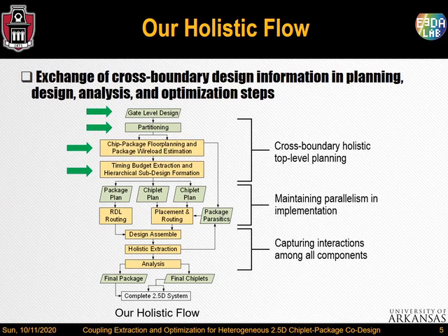The flow doesn't stop here. This is only the first iteration. As the package workload and timing budgets used in the physical design are just rough estimates, there is almost always some room for improvement. We use the analysis result of the first iteration to create new timing contexts for each part of the system and go back to the physical design step for the second iteration.